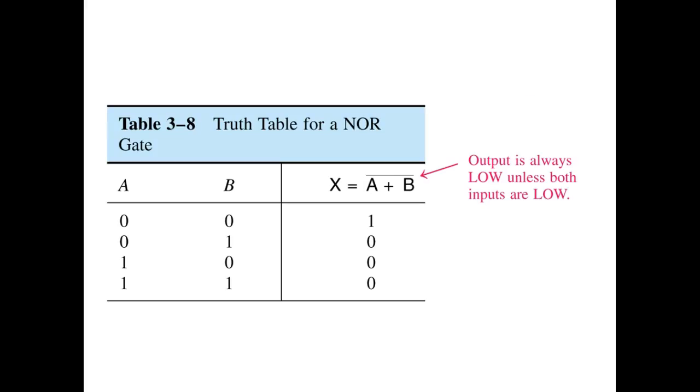So this is the truth table. So here's the Boolean equation. I start off with the output, then I put the inputs. The plus indicates an OR. And then what do we do? To indicate the output is low active, we put a bar across it. And that would be the Boolean equation for a NOR. So what would be the Boolean equation for a 3-input NOR?